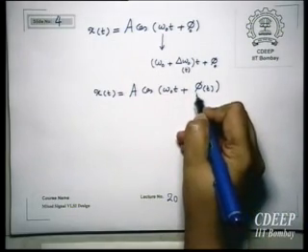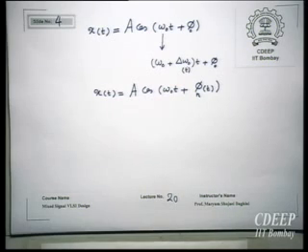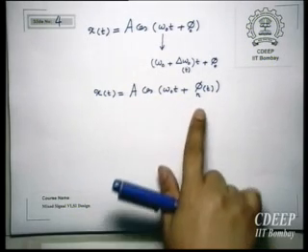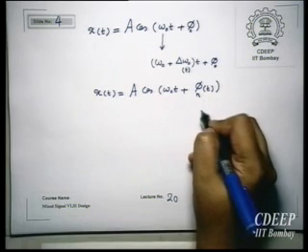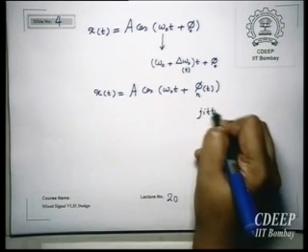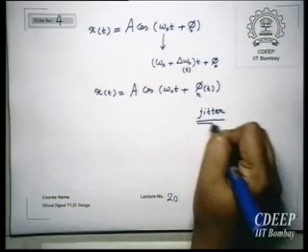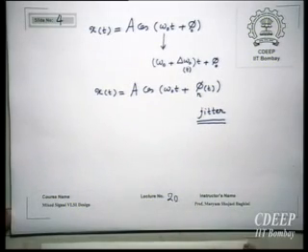In general, we call it phi n(t). Means that whatever variation we have, we include it in one phase which is changing with time, whether it is deterministic or it is not, and we call it phase noise. And this phase noise actually means the noise which is added to the phase. Okay, it is deterministic or it may not be. And this is actually what is called jitter. In fact, jitter and phase noise both originate from the same concept.